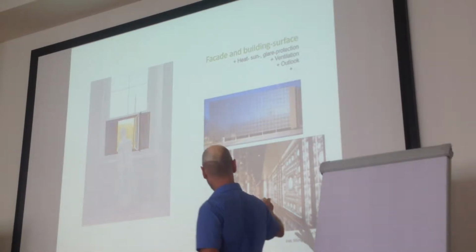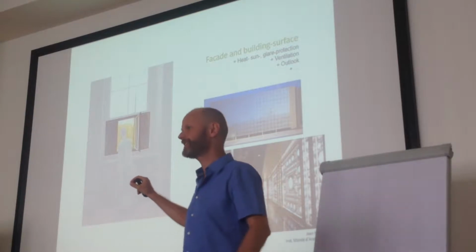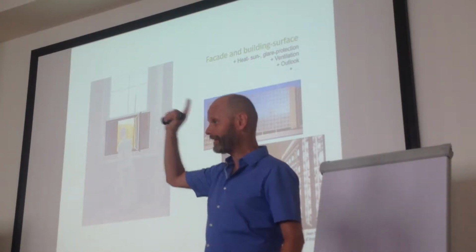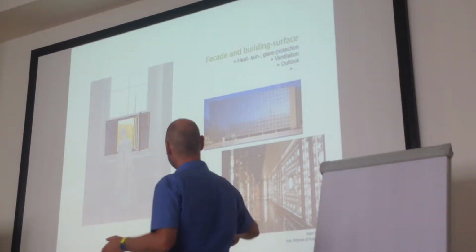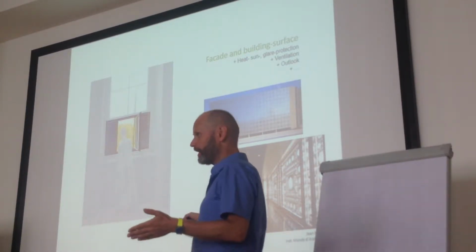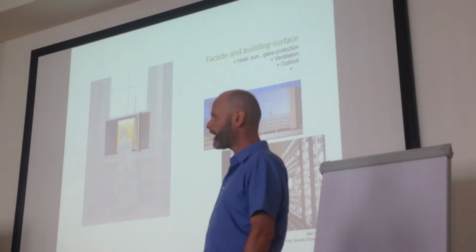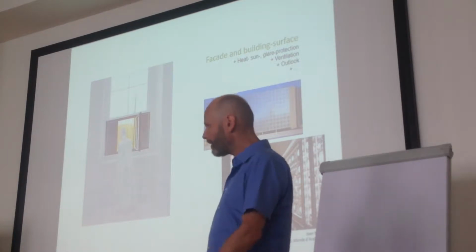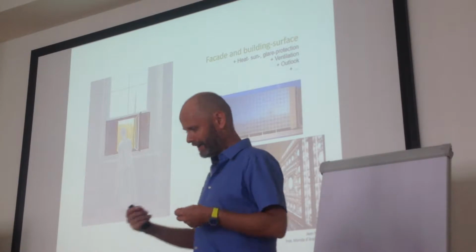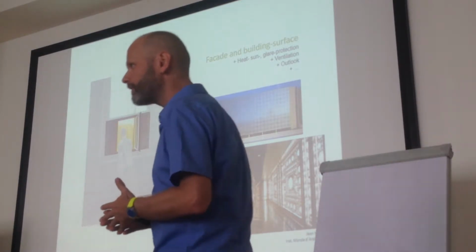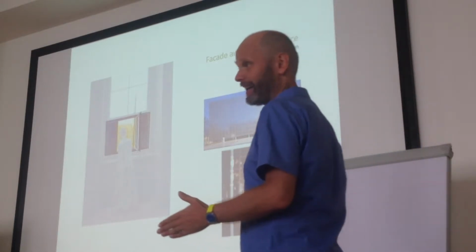what happens if the sun shading device is closed? What has to be done at the inside? The light has to be switched on. Exactly. So we have a very highly glazed building here, but on the other hand we have to switch on the lights. Because otherwise we get an overheating problem, and this is also a kind of mismatch, so to speak, that is observable in many highly glazed buildings.